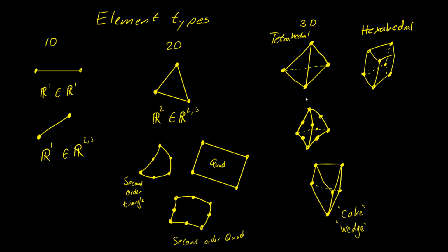So you have one dimension which is much larger than the other dimensions, and then you need to do the simplification. And I'll be talking about beam elements shortly, because we will be doing some SolidWorks stuff with beams. But we typically don't want to generate a huge amount of 3-dimensional elements when we're dealing with 1-dimensional entities or 2-dimensional entities. And that's why we have these.